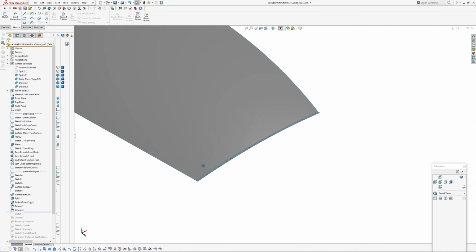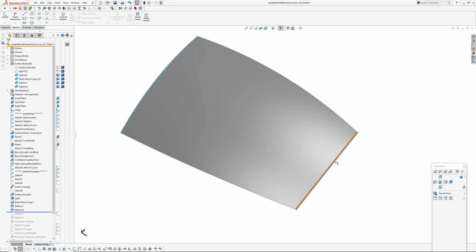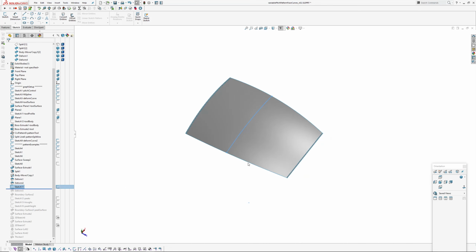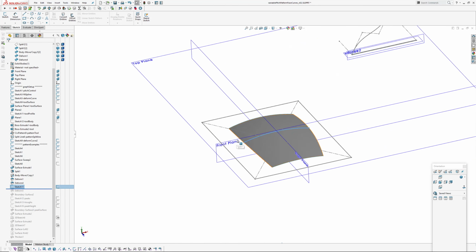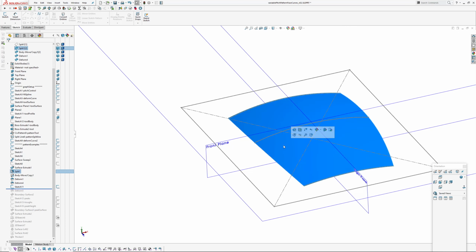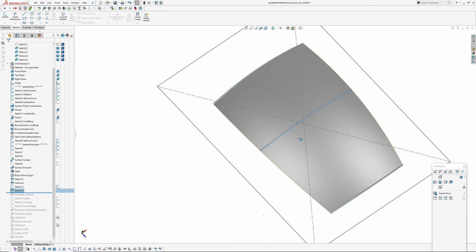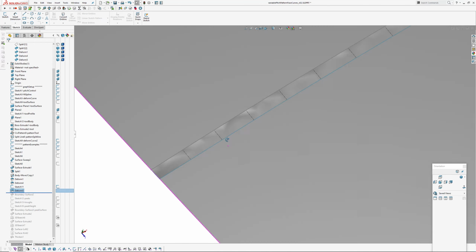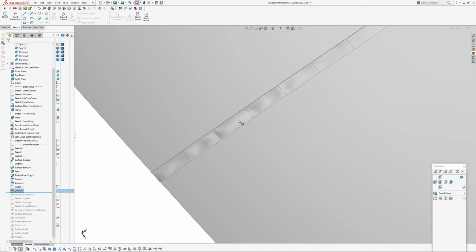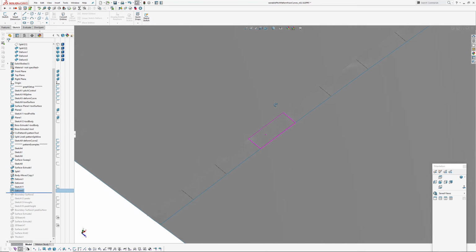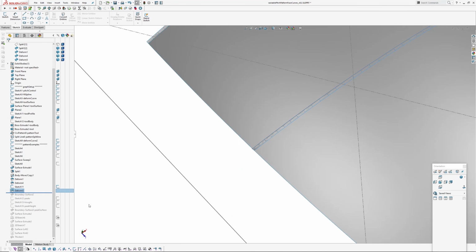So there I've deformed it to each end, and then I need to create a cross curve through the middle. To do that, on the front plane I've just made an intersection curve with the surface, so that will all update. So that's just an intersection curve, and then using that intersection curve, I've added that last deform tool. As I said, you can see the deform tool's surfaces are all wobbly, but where that vertex of the tool surface lies on that curve, it's coincident, which is all we need.